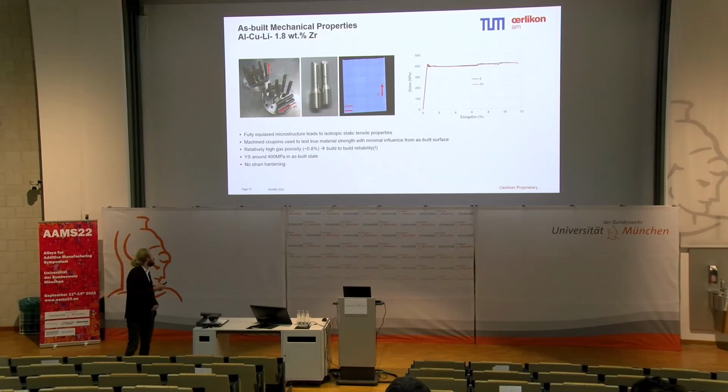What's interesting is that these process parameters were selected based on a process parameter mapping DOE that showed this set of process parameters having 99.8% density. We took that value based on single two-dimensional cross sections. We applied those parameters to this build job, just cylindrical tensile coupons.